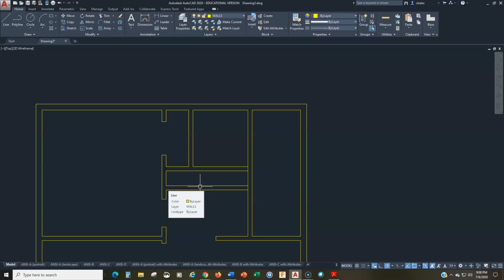That's the thing with architectural drawings. While it is, like I said, a bit confusing because everything is just lines and they're all horizontal and vertical, and you've got to make sense of it. Once you get past that or understand that and get into a workflow, there's nothing more complicated. There's no geometry. There's no weird commands. Notice I'm just using offset at this point. Offset, trim, a little bit of extend, erase, and that's it.